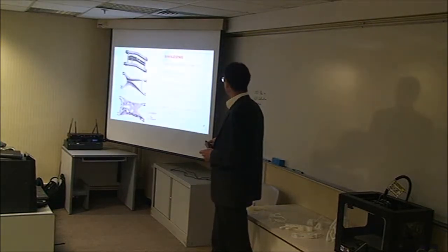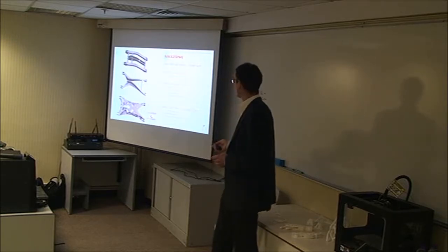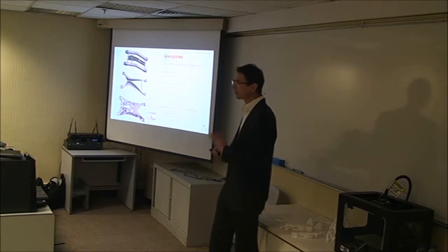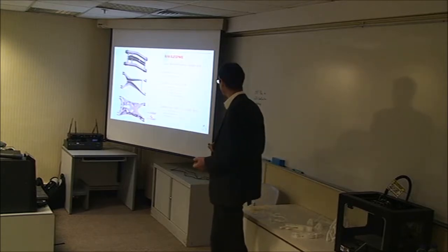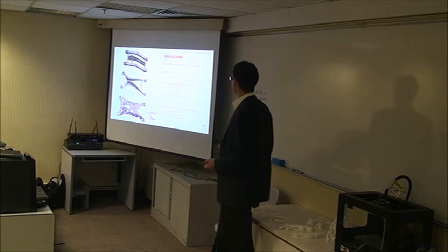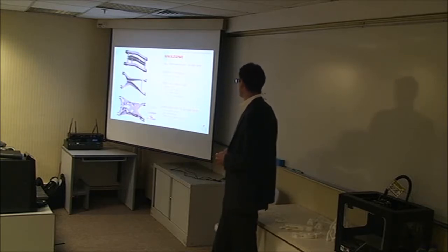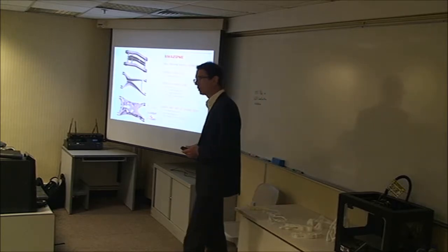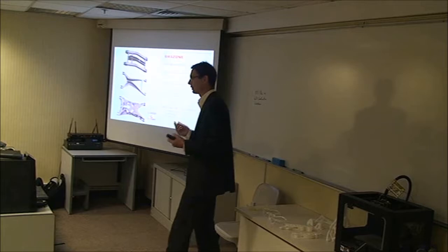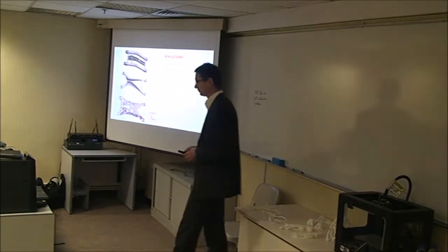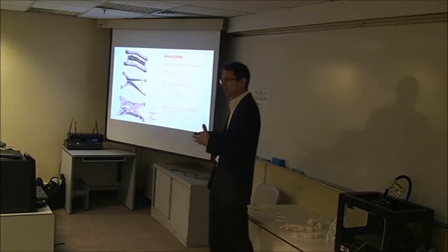So at the beginning, the initial part was already optimized with casting, boundary conditions, manufacturing constraints, already lighter, with cost reduction because of fewer welding lines. But then 3D printing brought even more weight saving, and time reduction for the tooling process because you print the tool and not machine the tool.